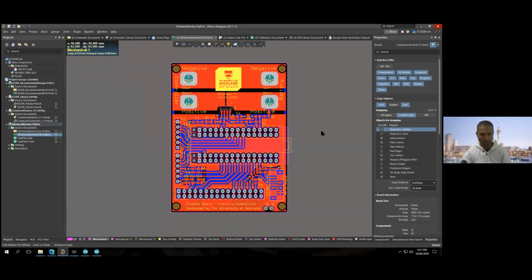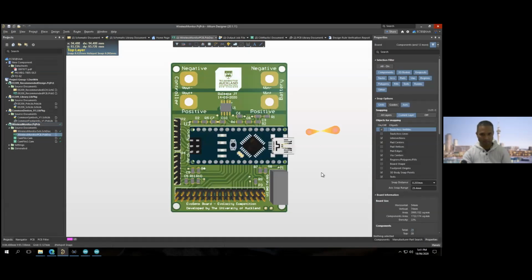Would this be providing us with a printed board? Yeah, it's a printed board where you can connect up the Arduino. It already has the ACS 712 and the voltage divider, and connects onto the Arduino itself, A0 and A1 pins. You connect the battery up from this end, you connect your control on this end, and you load the program you've written and it will be able to print all the voltages and currents and power. It also has a header here that you can connect up to your Bluetooth module and the LCD panel.